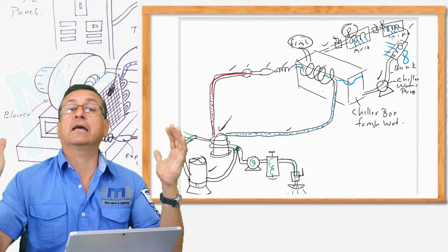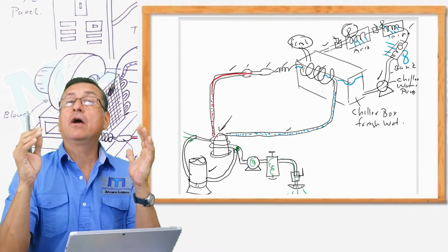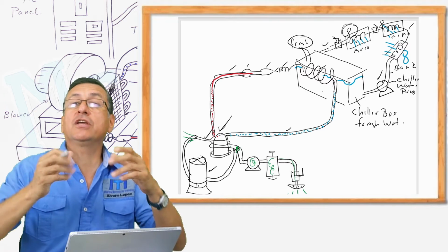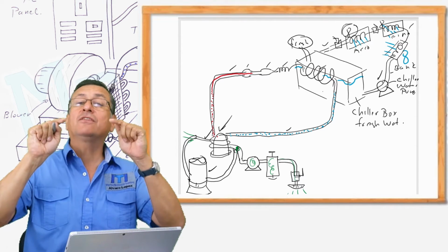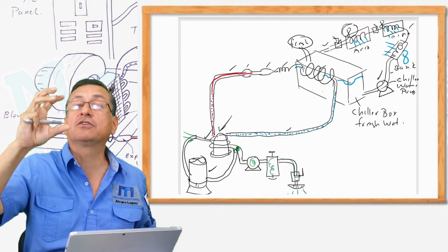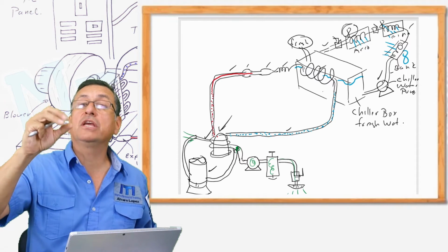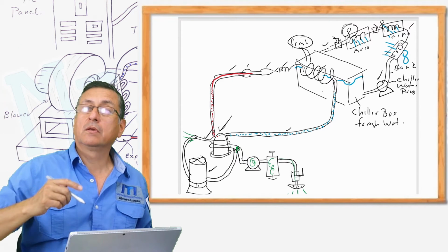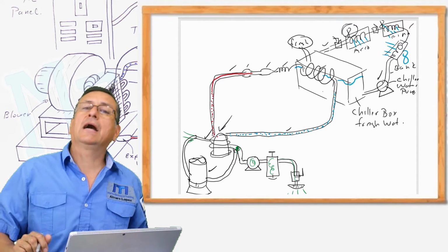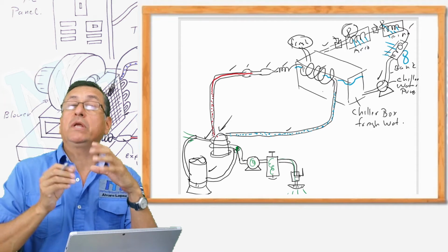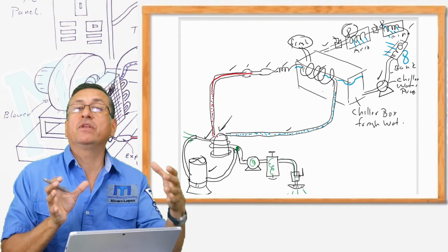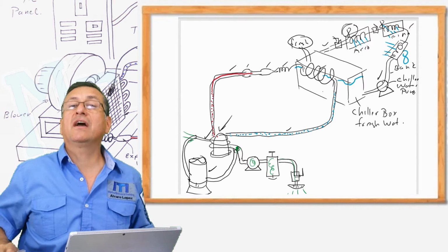But it is like a self-contained unit. You have one heat exchanger with raw water for the condenser, and another heat exchanger with fresh water for the evaporator. That fresh water goes out and enters different small radiators, small coils, small air handlers. Each air handler is located in one office, in one room. And it continues through 6 air handlers and returns. Okay. In between, the evaporator is located inside the box with fresh water, and in each air handler you only have fresh water.